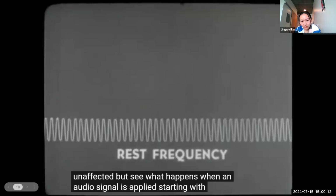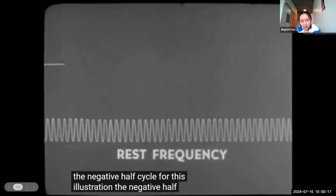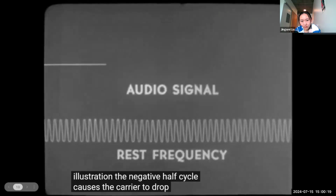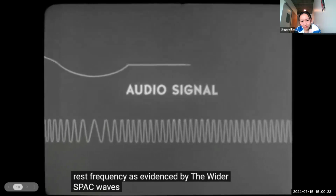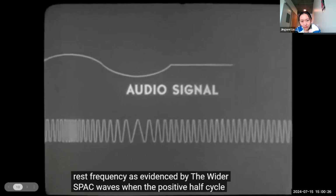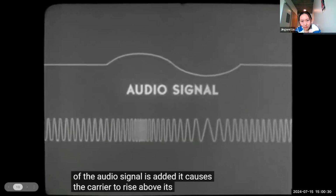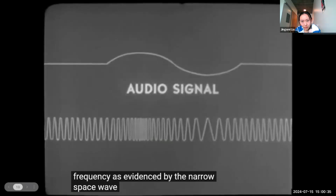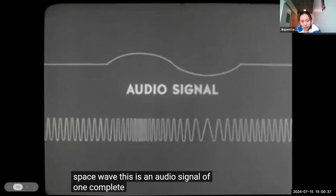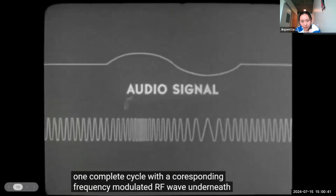But see what happens when an audio signal is applied, starting with the negative half cycle. For this illustration, the negative half cycle causes the carrier to drop below its rest frequency, as evidenced by the wider spaced waves. When the positive half cycle of the audio signal is added, it causes the carrier to rise above its rest frequency, as evidenced by the narrow space waves. This is an audio signal of one complete cycle with a corresponding frequency-modulated RF wave underneath it.